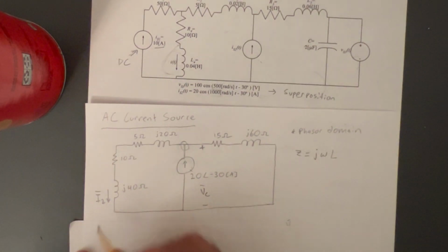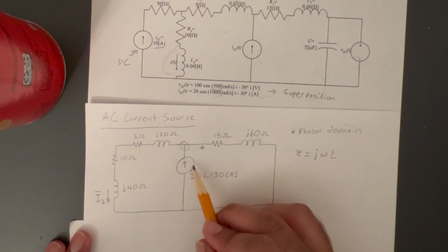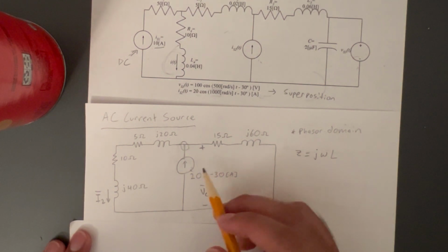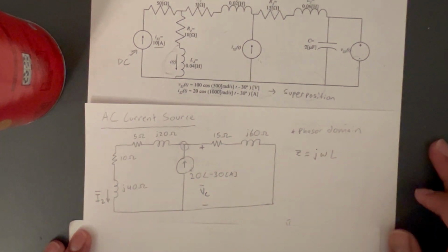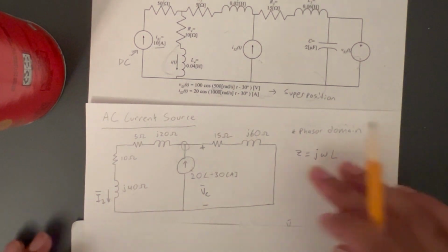I've also defined I2, which is the value that we're looking for. An important thing to note with defining values on a phasor diagram is that they must be phasors themselves. They can't be in the time domain, because in an AC circuit, all the currents and voltages involved will be sinusoidal, since there's an AC source present.